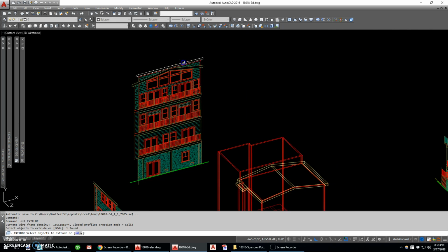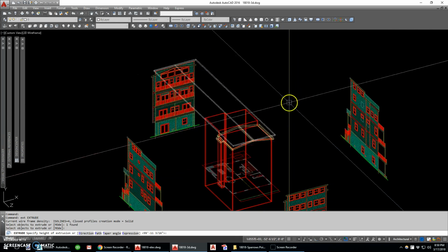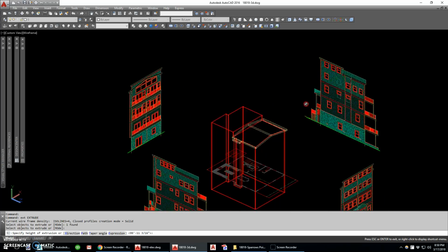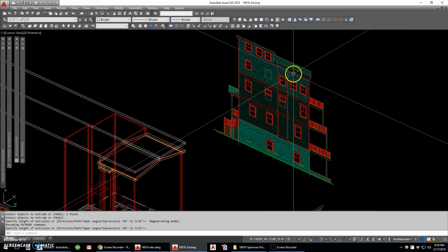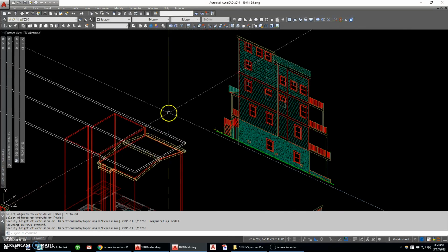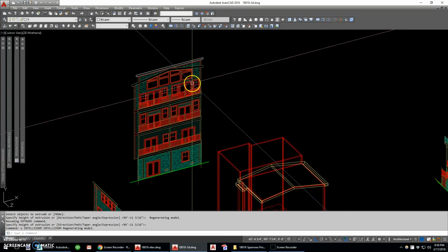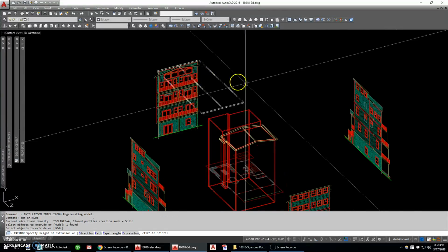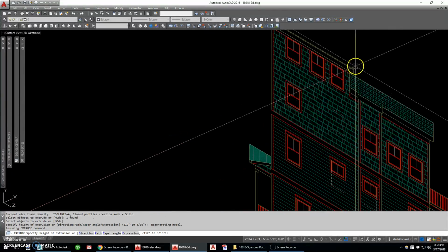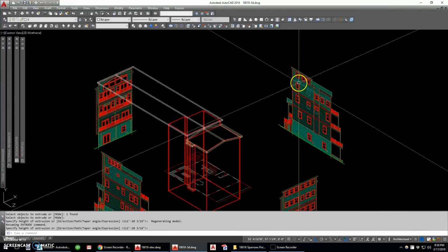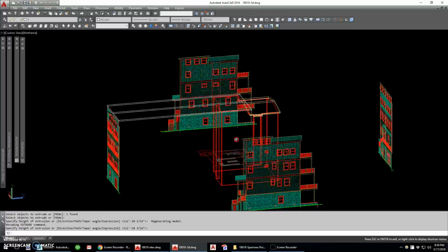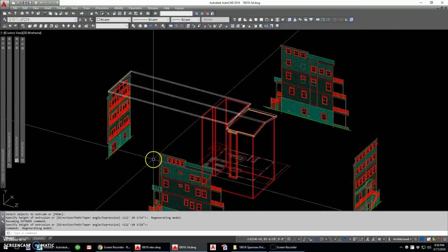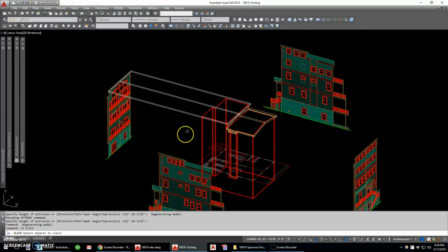Now I'm going to extrude this roof. Again, I'm going to orbit in my command and use the elevation as a, oh shoot, that was the wrong roof. I'm not thinking. So I undid that. I'm going to extrude this roof to the end of the upper roof. Now in this elevation, again, the roof jogs. I'm actually going to trim it to the furthest jog for now.